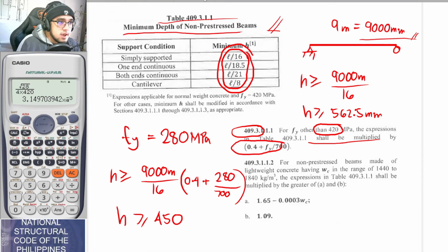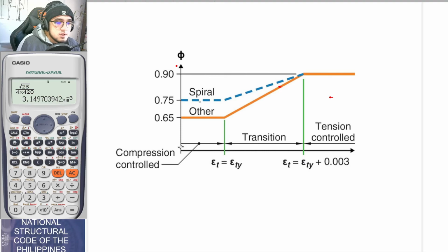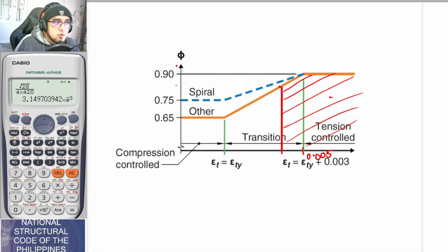Let me repeat, guys, in this particular graph, if this is 0.005, and according to NSCP, they allow 0.004, approximately that is, let's say, here. So 0.004, let's say that is the region. So according to NSCP, once again, you can only design your structure to be in these regions. You are not supposed to go to the region here. So this is not allowable already according to NSCP.